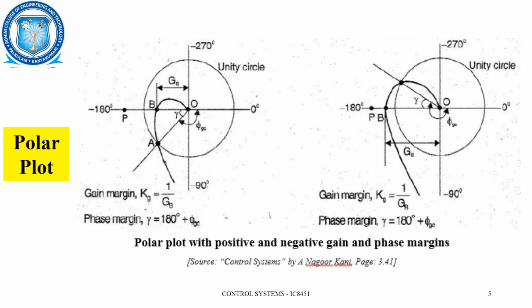This is one case. You can see here that the graph is outside the unity circle. It is going outside the unity circle. In such a case, this is the gain margin value calculation. We have to find out GM. We can see that the 180-degree line is cut by the polar graph outside the unity circle. So this is your magnitude value.